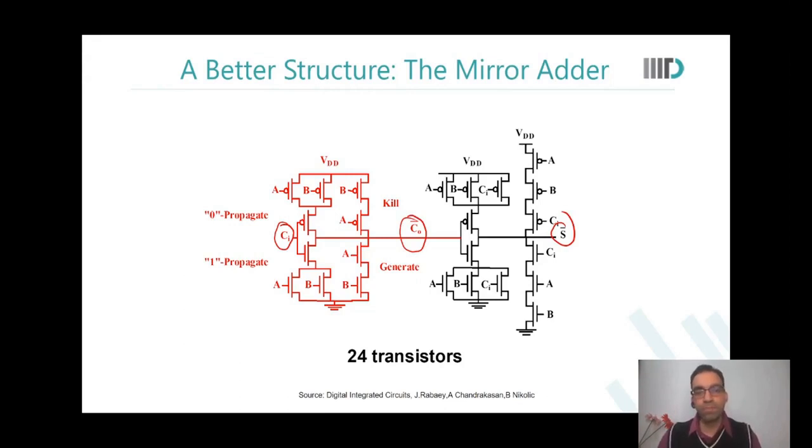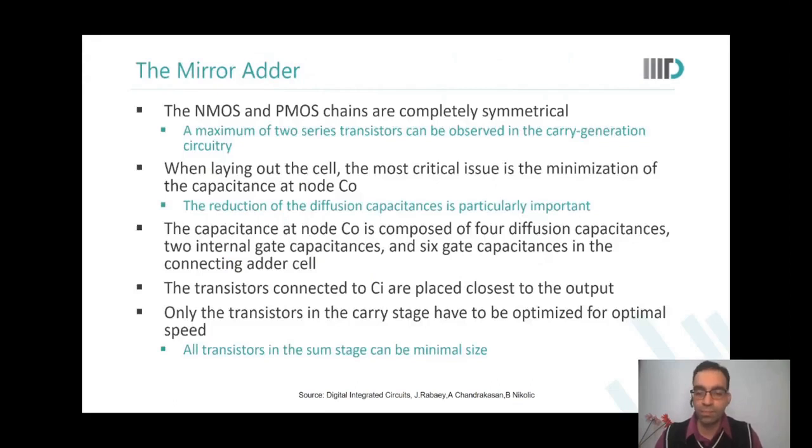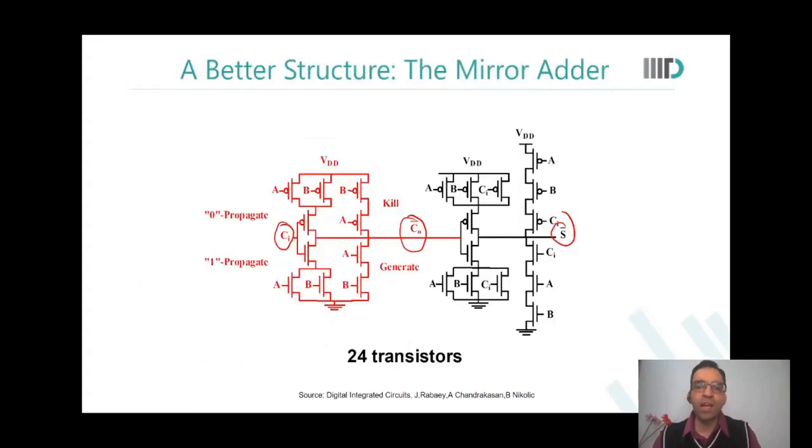Okay? So you can, at your own leisure, evaluate that this works fine. This is fine for the functionality that you want to achieve for both C0 and S. Sir, this particular topology will be valid only if we have an even number of stages, right, sir? If we have an odd number of stages, then once again we need to add an inverter at some stage. That we can just add on the last stage. Yes, so just one inverter will come. It will not come 25 times. Yes, sir. So that we can always terminate appropriately. Yes, simple.